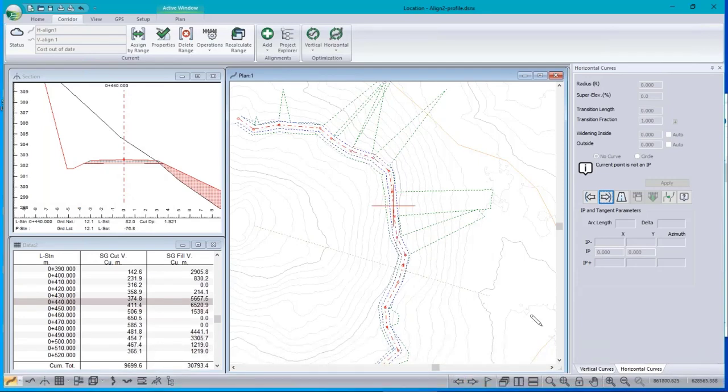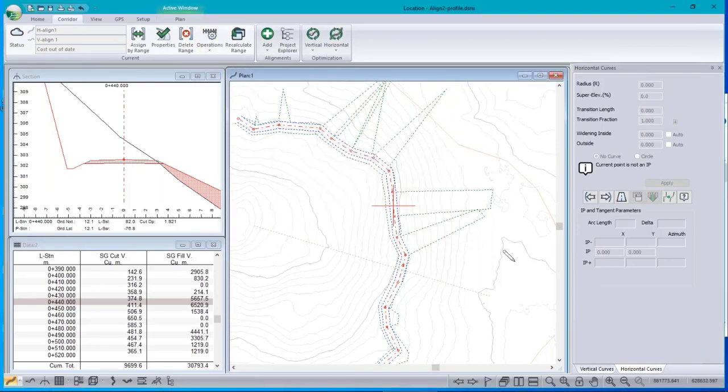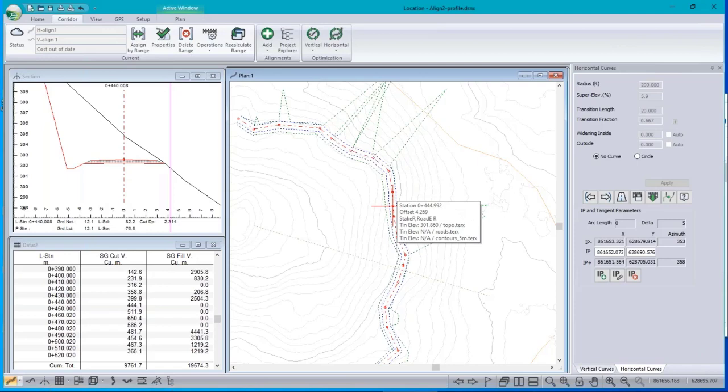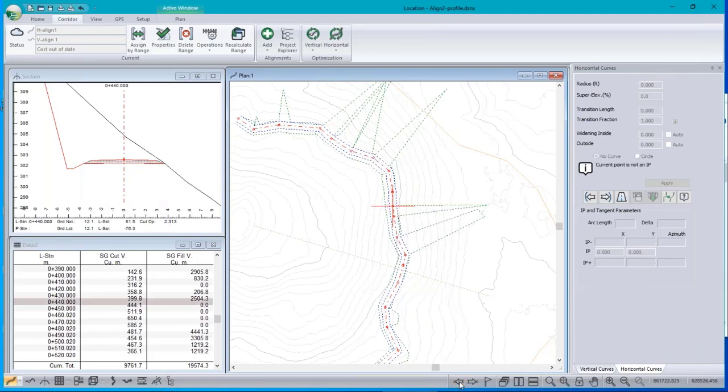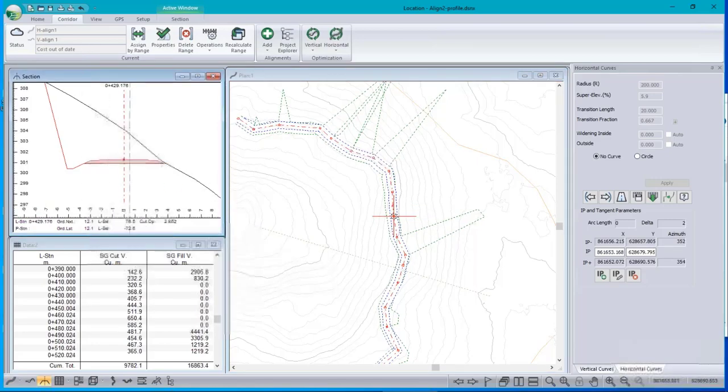I'm just going to go back to the middle or so, and then I can either move it horizontally by hand, or remember this thing here said that I could use Control F. Let's try that. So I'm sitting on this cross section here. There's no intersection point. I type Control F, and there, it fixed that one cross section. And unfortunately, there's another problem in between, and it's right next to this point. So what I'm going to do here is I'm going to just manually move it over a little bit, and that fixes up that section there.